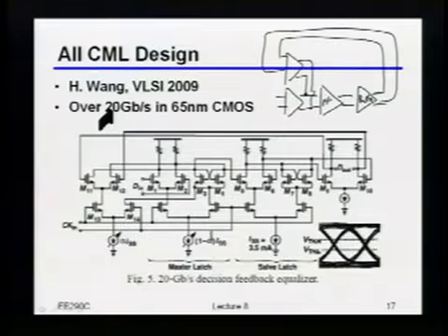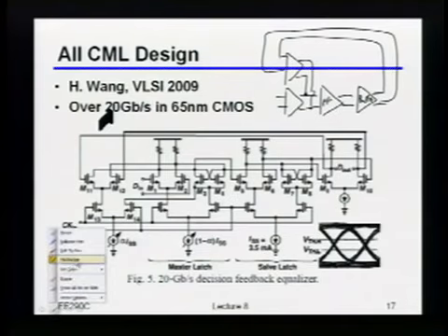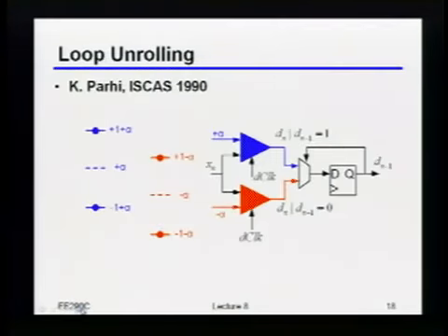Okay? So indeed, you can actually get up to some pretty high speeds, but even that sometimes is just not good enough. Okay? So we'll basically close with this for today, but the last technique you can pull, which again is really mostly focusing on that very first tap, where it's just hard to get that kind of speed, is what's called loop unrolling. Okay? So this idea is very similar to what you do in carry look-ahead adders. So the idea here is the following.